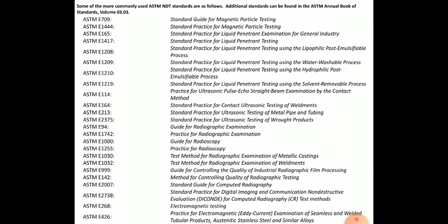The next one is ASTM E165, the standard practice for liquid penetrant examination for general industries, and further continuing, another code, ASTM E1417, the standard practice for liquid penetrant testing, and then ASTM E1208, the standard practice for liquid penetrant testing using the lipophilic post-emulsifying process.